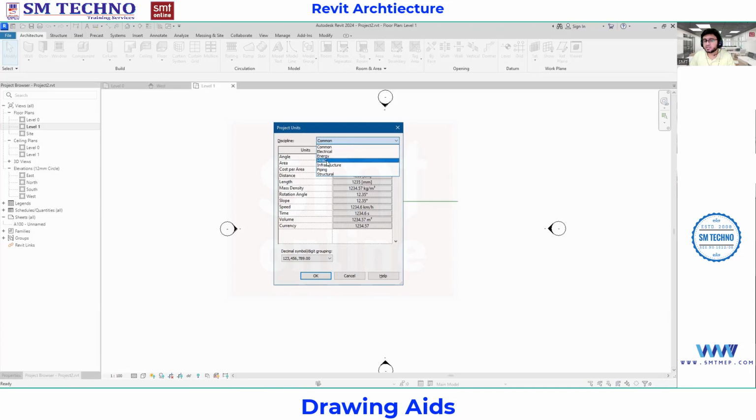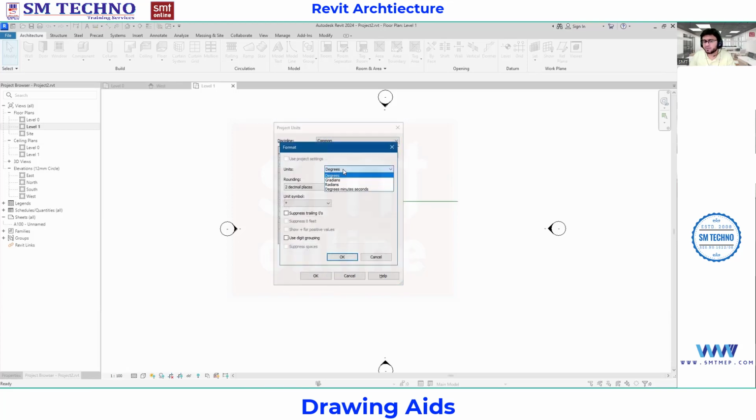Common, electrical, energy, HVAC, infrastructure, piping, structure. We are working with common. So which angle? Angle will always be in degrees. You can go with others also, like radians, but we always follow degrees only. So what is the degree decimal you want? 1 decimal, 2 decimals, or 3 decimals? Like 23.25 degrees, 25.255 degrees. That will be defined with your decimal. Like 1 decimal is enough for the degree, 0.1 degree is enough.